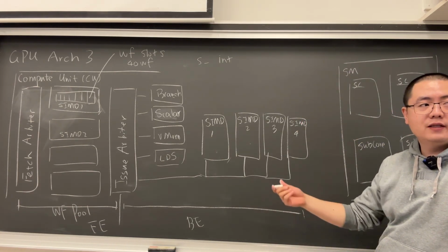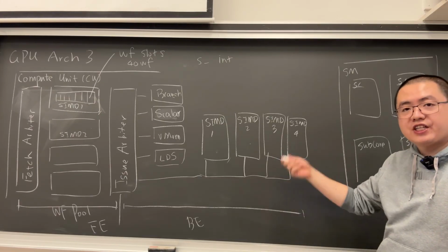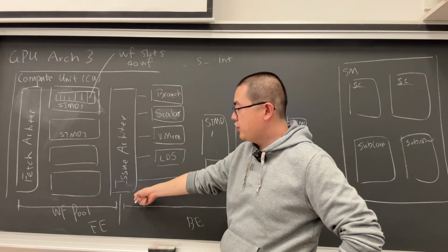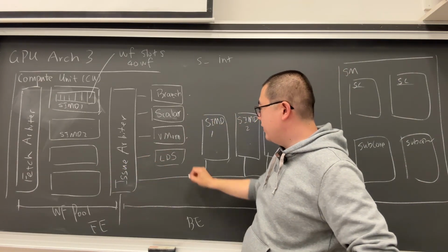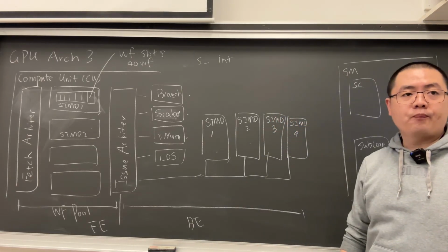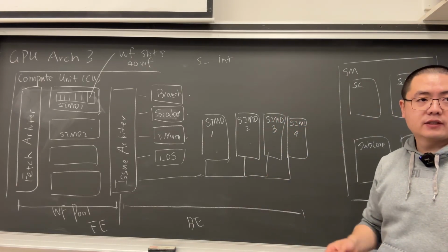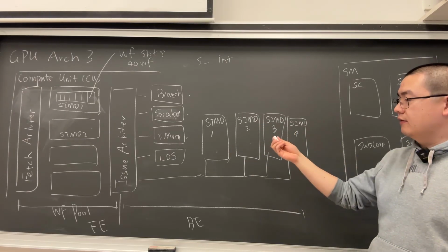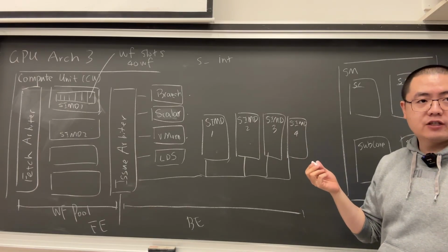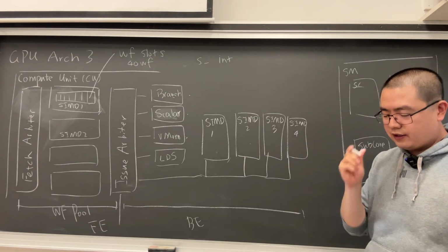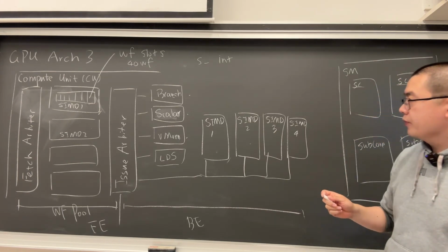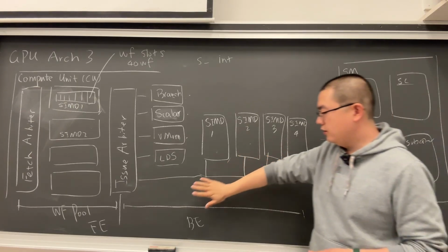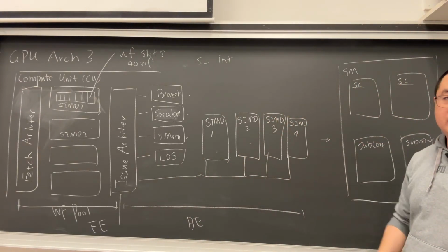Okay, but AMD just has more resources that are shared by these subcores. So for example, the fetch arbiter is shared, issue arbiter is shared, branch, scalar, vector, memory, LDS are shared by all these AMD components. So that's why AMD prefers to draw this type of diagram in this way rather than that way. Then there's definitely a shift after the RDNA age. And we will slightly talk about the RDNA differences, hopefully by the end of today's lecture. AMD is also shifting more and more towards this style, but let's still learn the classic AMD architecture, which is basically implemented in this way.